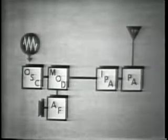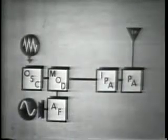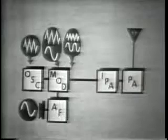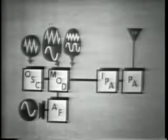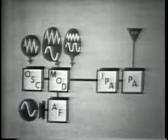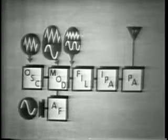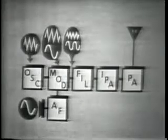Of course, we use a crystal oscillator of low frequency RF to generate a stable carrier. When we modulate it with an audio frequency, the two signals are mixed together in a balanced modulator, which is designed to cancel out the carrier and filter the modulating frequency in its output and produce only the two sidebands, the upper and the lower. We then insert a filter which will pass only one of the sidebands, and of course we can select either one, and we'll reject the other one. Thus we have only one sideband to be transmitted with all of the transmitter's power.